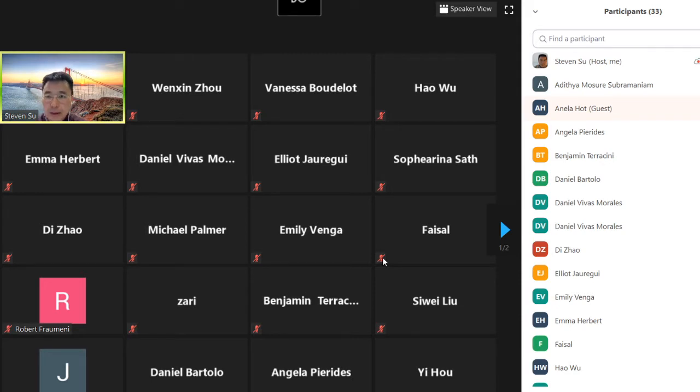So the instrumentation amplifier is very important for this project, like for analog signal conditioning. For the weak biomedical signal, for example, ECG, EEG, and EMG, the first stage is amplification.